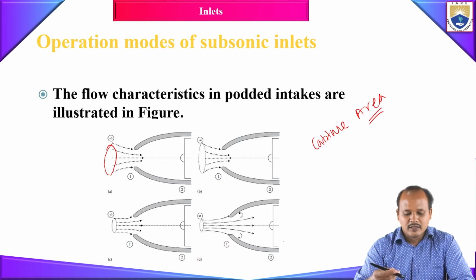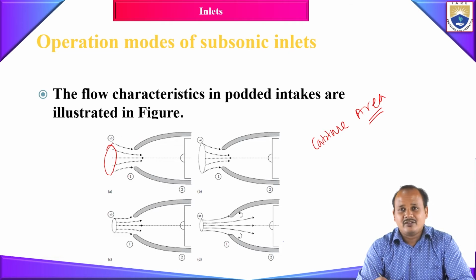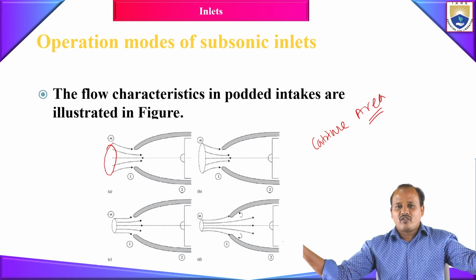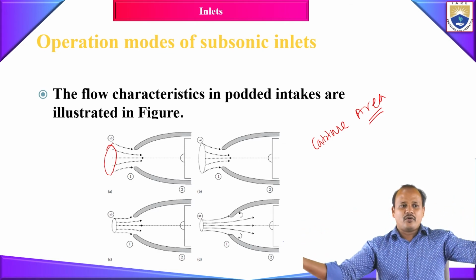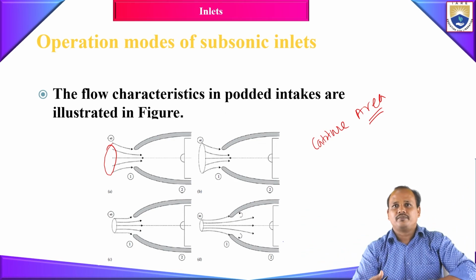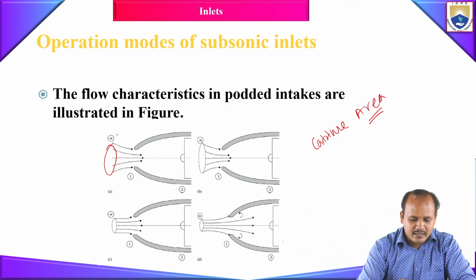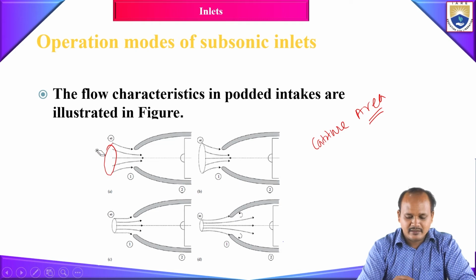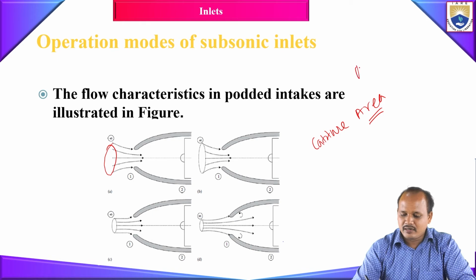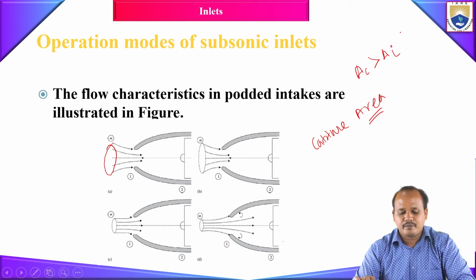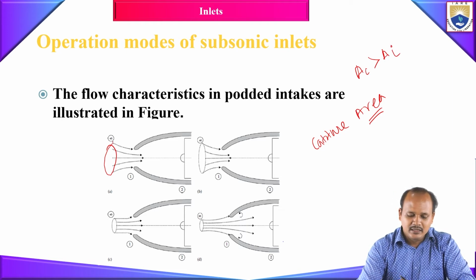Okay, so if I take a low speed operation, like a still operation where the aircraft is still, that means air from your entire surrounding will come towards your engine. When you compare the capture area AC to your inlet, AC is much greater than the area of your intake. That means here the area is more and the intake area is less.